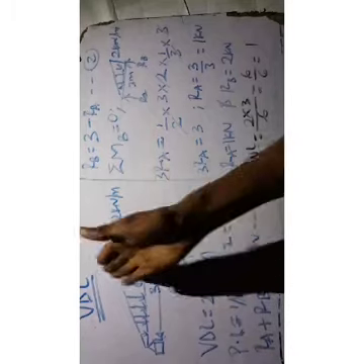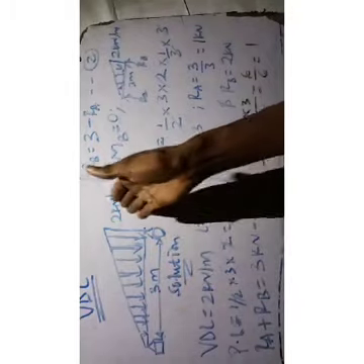So just make use of the formula, but you can't just make use of the formula like that. To prove this, I come again: you carry the parameter outside, you write your RA plus RB equals 3, equals the point load. Point load, you convert it using your area, which is half base times height. What is the base? 3 times height. You have your point load, then you write RB equals 3 minus RA.